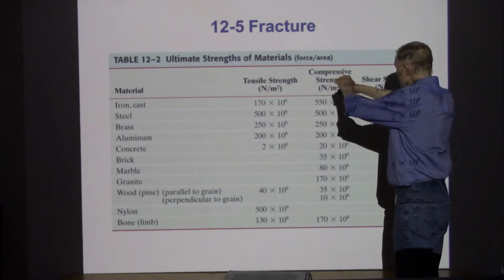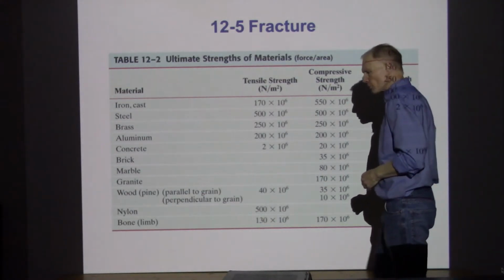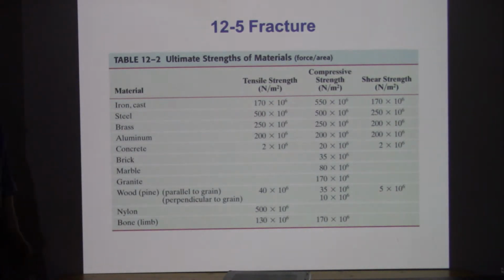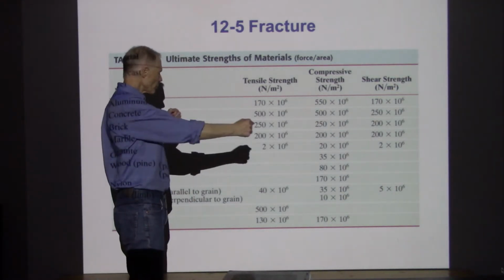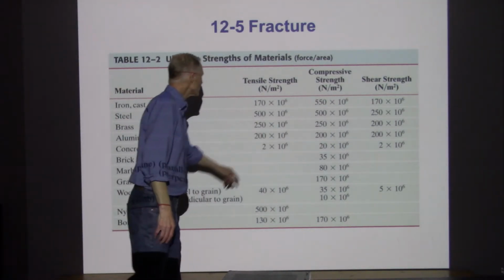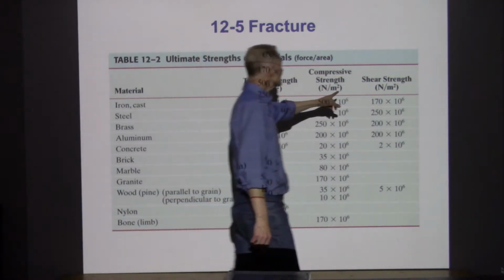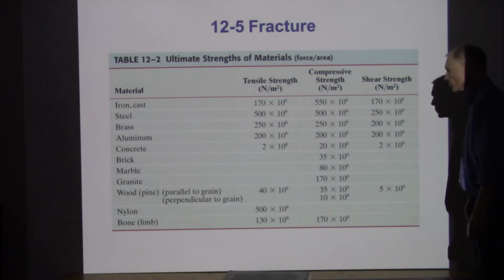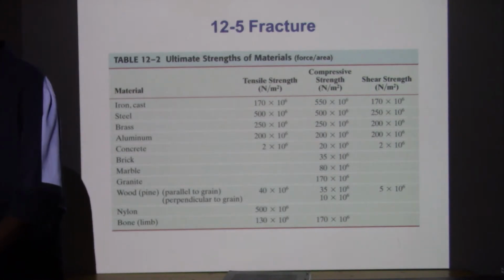And so maybe these are the two columns I was thinking in terms of, I guess, ultimate strength, but even under the amount of elongation, I don't know, I'd have to go back and look and see what does happen to concrete if we try and stretch it out. Anyway, its compressive strength is 10 times as large as its tensile ultimate strength. And then here is shear strength. So shear strength is showing under shear stresses what's the maximum shear stress this material can deal with.